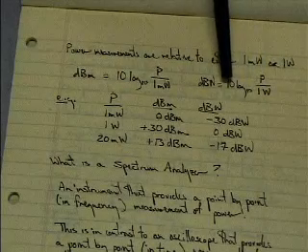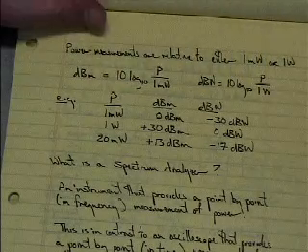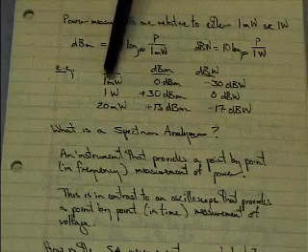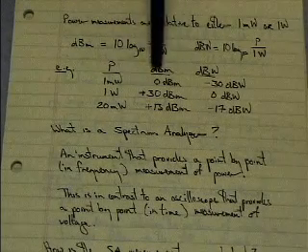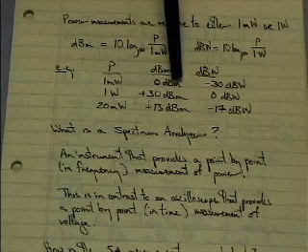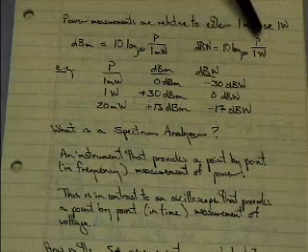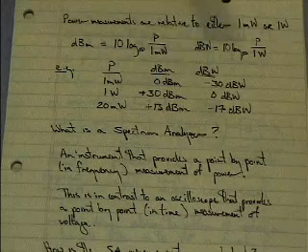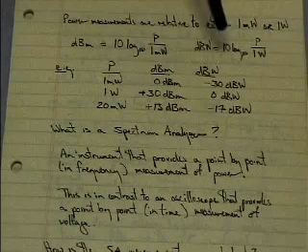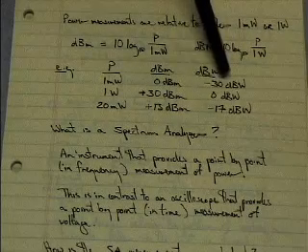Log base 10 again and multiply by 10. So here's a couple of examples of what we might have. A 1 milliwatt signal relative to 1 milliwatt in a dBm scale gives us 0 dBm. Relative to 1 watt, it's 1/1000th. A milliwatt is 1/1000th of a watt, and you take the log base 10 of that, multiply by 10, and you get minus 30 dBW.